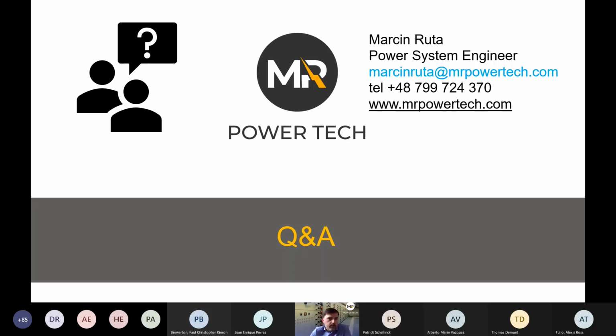Some countries just adopt NFPA and IEEE 1584 as a guide to assess arc flash, and I would say it's quite a good approach because it's complete. So if you follow NFPA and IEEE 1584, IEEE 1584 for calculations for most of the systems, and NFPA 70E, let's say you pick specific parts of NFPA 70E related to electrical safety, then you are on the good side.